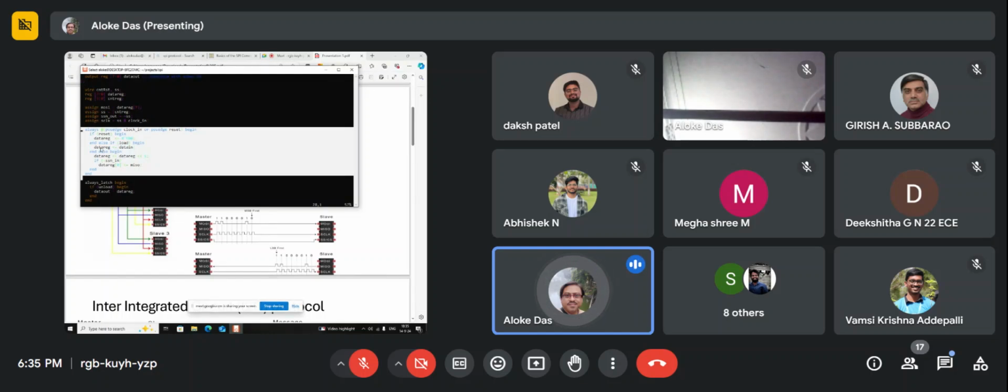This is the heart of this Verilog file, the heart of the protocol. So posedge clock in means this is the clock reference, at a rising edge or reset. I have defined data_reg as an 8-bit register, and if load, data_reg equals data_in, and otherwise data_reg does a left shift.